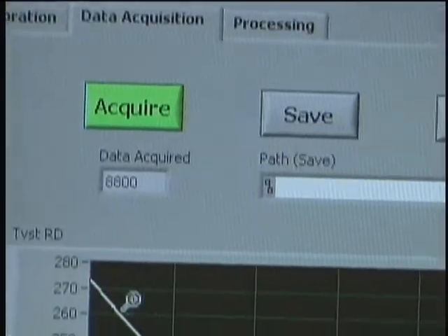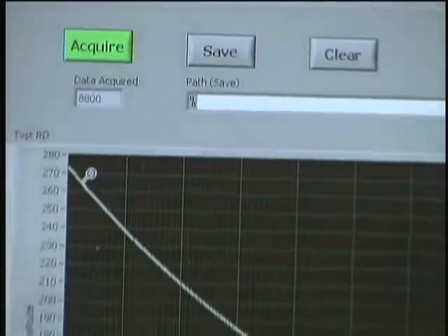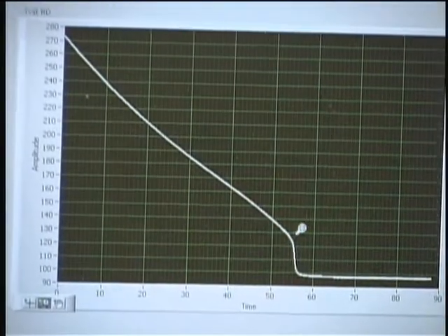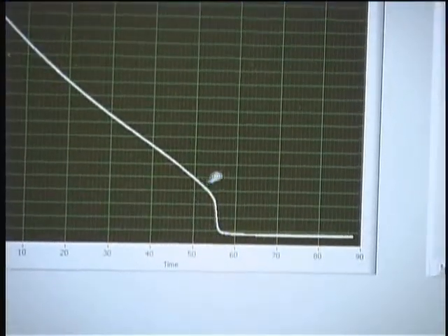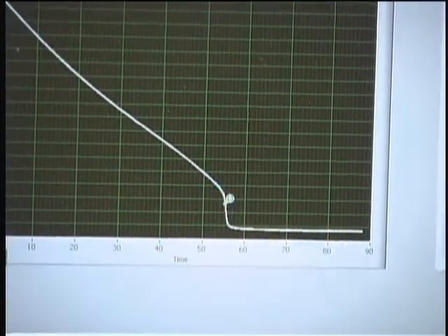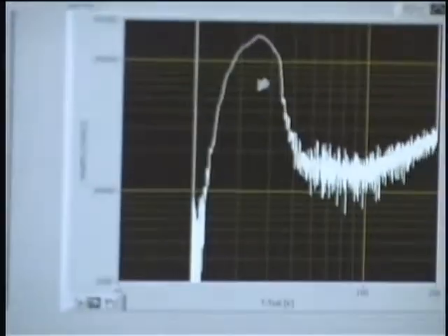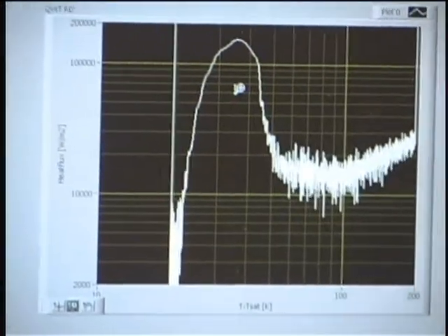So if you look at this curve, there's a reasonable decline in the temperature, and then around the Q max you get a very rapid decrease in the temperature. This is where the fluctuations make a big difference, and that corresponds to the Q max on the boiling curve.